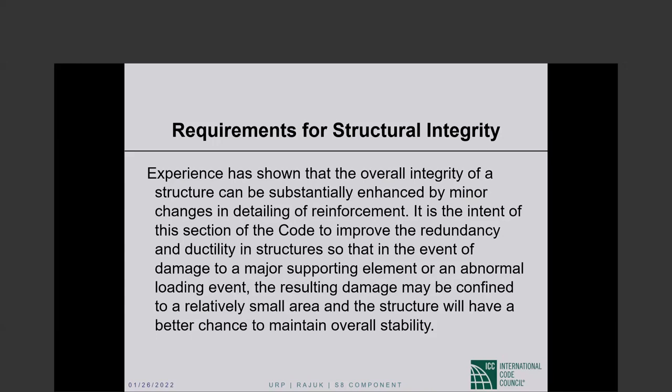So the maximum limit of gap between two layers of reinforcement in beam, top or... The questions are framed in a very strange way. No, this question is probably not strange. So the minimum gap between the upper layer and the lower layer of reinforcement is 1 inch. Okay. So the question is, is there an upper limit on that gap? The answer is there is no upper limit.